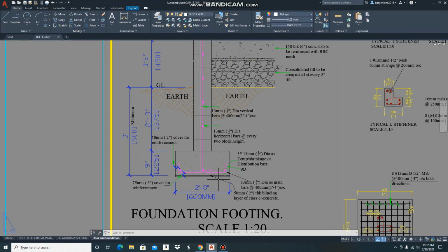Remember, stress is equal to force over area. When you increase the area of your footing and divide that area into your load, if your load doesn't change and you change your width of your footing, which means you're going to change the surface area, when you divide that area into your load, you're going to end up with less stress, providing the weight of the wall or the building remains constant. So that is key to note.